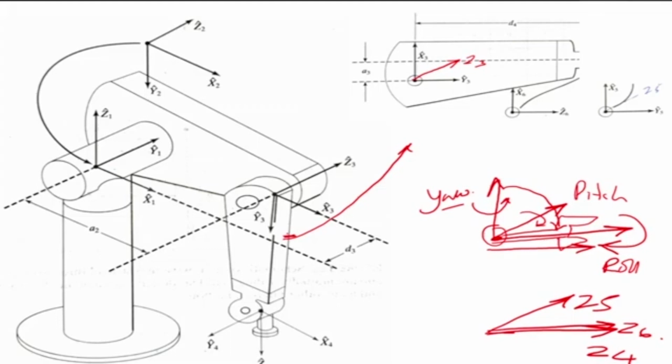Whether it is this side or this side, it is relative. If you put it on top, there is a problem in assigning your DH parameters. So if you look in the textbook or anywhere, that is the reason for the Puma robot the Z4 and Z6 seem to be along the same axis, but it is relative.